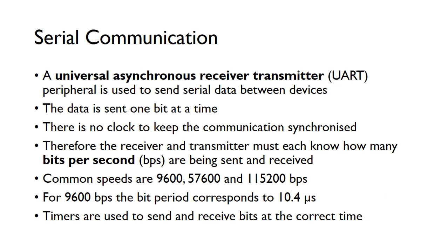So another application of timers in microcontrollers is in serial communication. Pretty much every single microcontroller has a UART peripheral. This is known as universal asynchronous receiver transmitter, and this essentially is used to send serial data between devices. The data is sent one bit at a time.